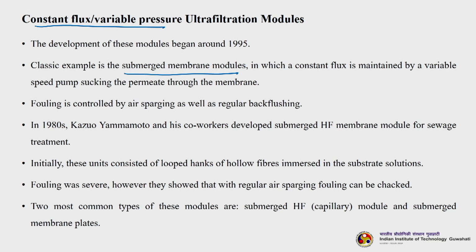Fouling is controlled by either air sparging as well as regular back flushing. In the 1980s, Kazuo Yamamoto and his co-workers developed submerged hollow fiber membrane modules for sewage treatment. Initially these units consisted of looped hanks of hollow fibers immersed in a substrate solution. Fouling was very severe. However, they showed that with regular air sparging, fouling can be minimized. The two most common types of these modules are submerged hollow fiber, that is capillary modules, or submerged membrane plates.